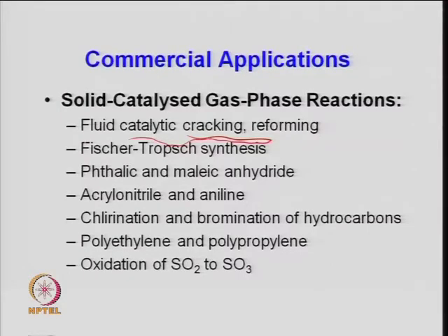Then for the Fischer-Tropsch reaction, they are also looking at this kind of system, where the catalyst is bubbled or fluidized, or a slurry bubble column reactor is generally used, because it is a highly exothermic reaction. But when it is a fluidized bed, the control of heat is better. Whatever heat is generated can be removed, and that is the advantage here.